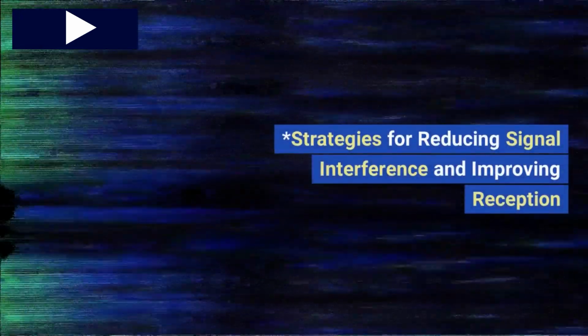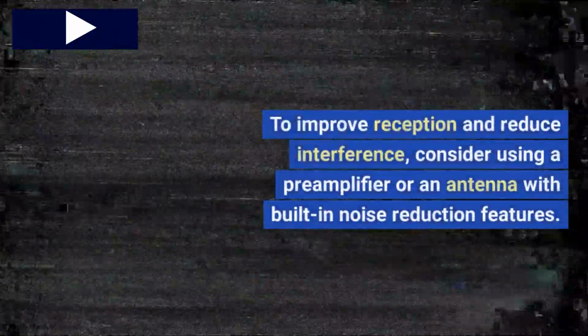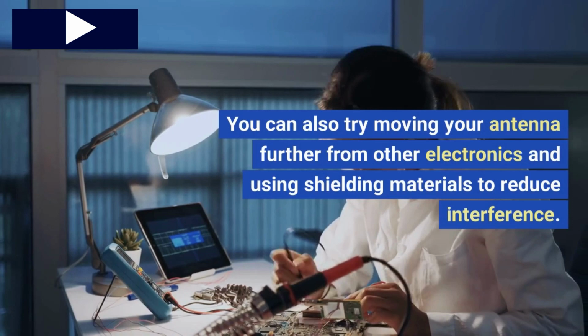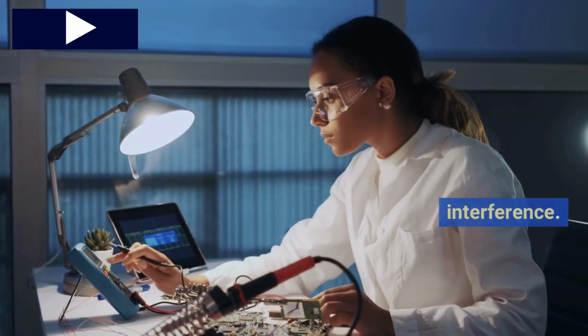Strategies for reducing signal interference and improving reception. To improve reception and reduce interference, consider using a preamplifier or an antenna with built-in noise reduction features. You can also try moving your antenna further from other electronics and using shielding materials to reduce interference.